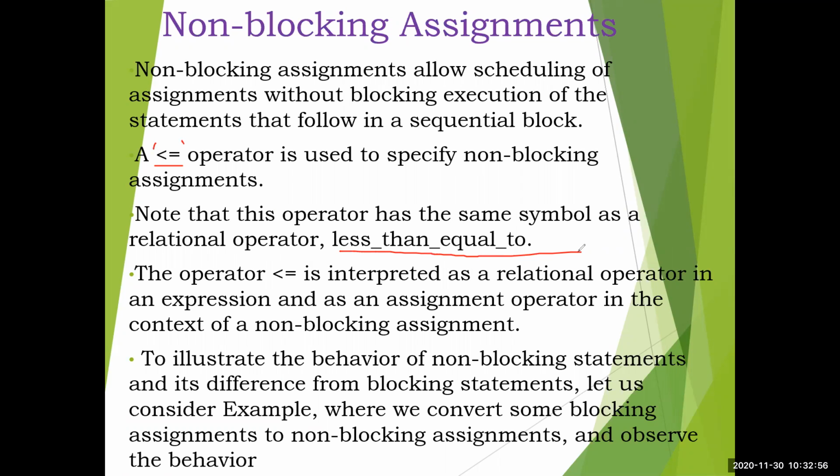When it is written in an assignment, it is a non-blocking assignment. Otherwise, in an expression, the operator is interpreted as a relational operator, and as an assignment operator in the context of a non-blocking assignment. So the same operator is used in both cases. In the case of an expression, it will do the less than or equal to comparison and give the logical answer.